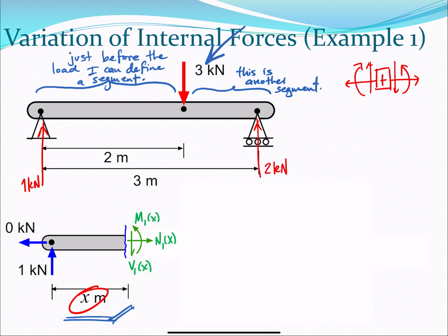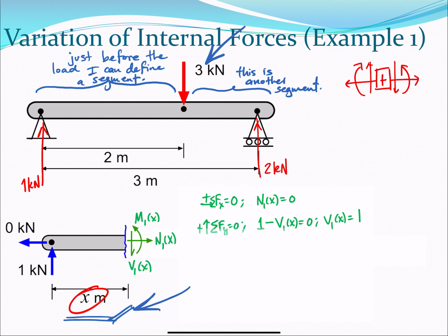So every time the load changes, or you have a reaction, or you have a new load, you have to define a different segment. For example, this is my first segment, and my variable x is defined from the origin to some arbitrary point just before the load. And then the next segment, I can, actually, very nice, let's start defining our equations before we jump into the next segment. Okay, so let's put it in practice.